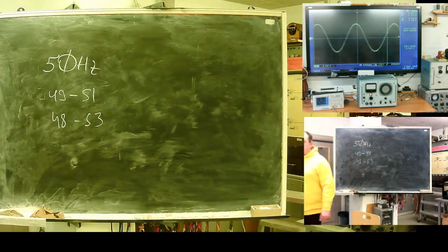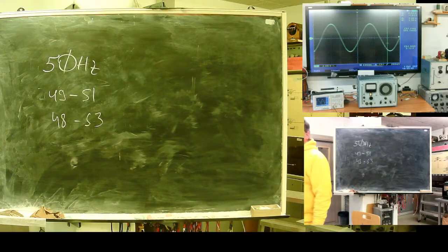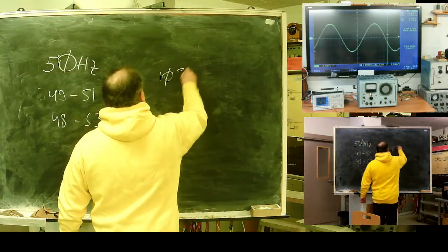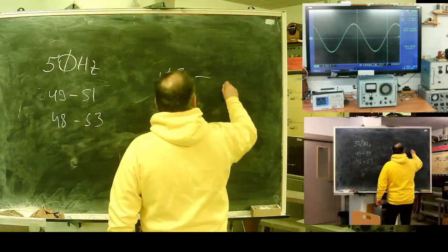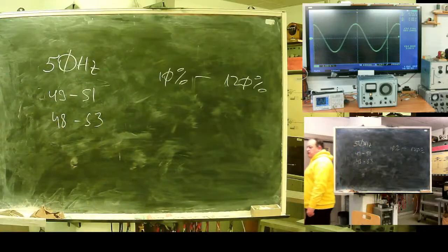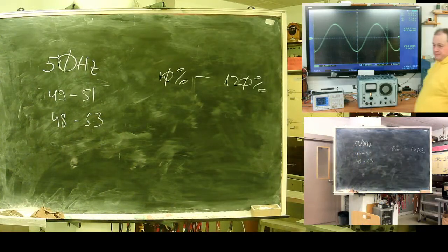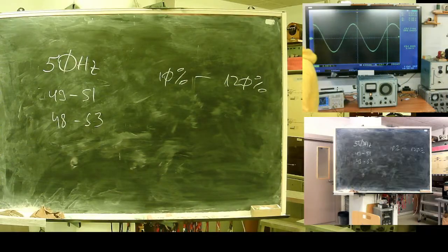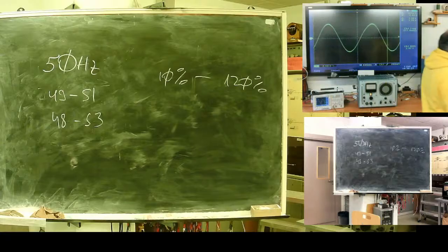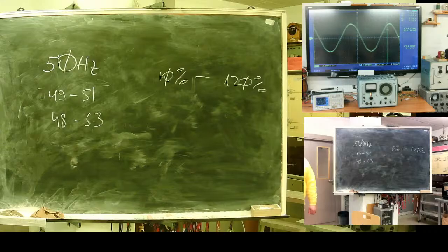If we speak of hydro turbines, the typical range is from 10% of rated up to 120% of rated rotation speed. So if your device is intended to operate in hydropower, your possible frequency range should be extended up to 120% of rated frequency. For wind turbines, maybe up to 200%.